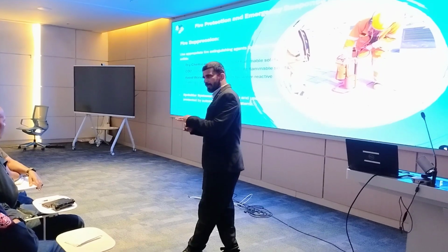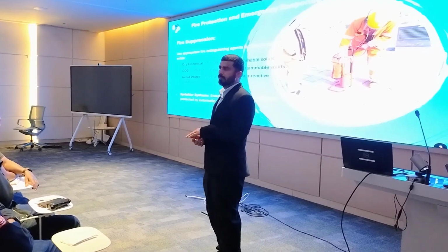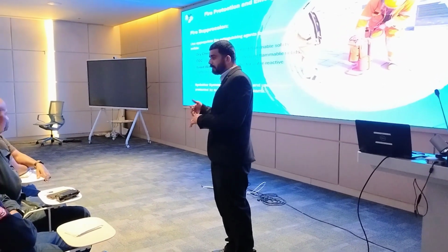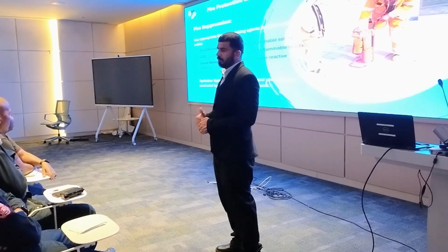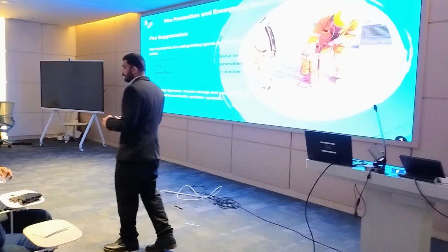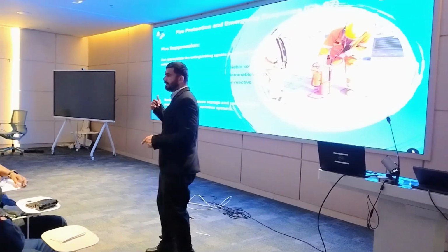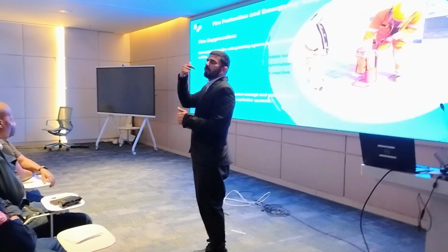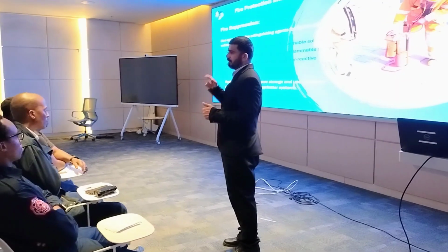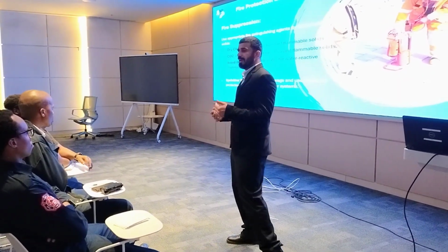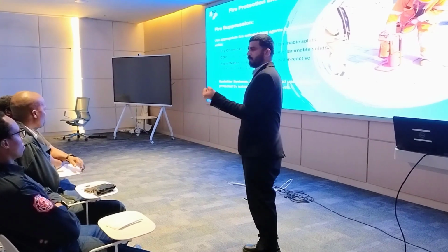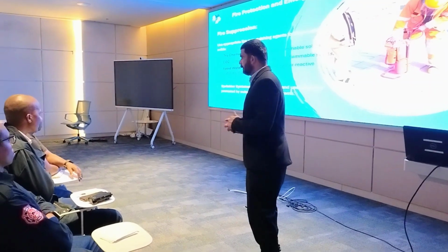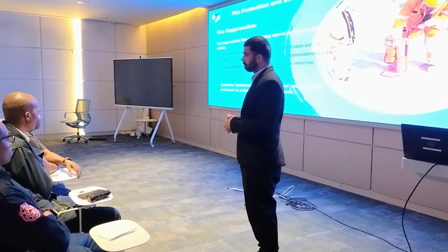Second, we have firefighting equipment: a fire hydrant, CO2, and DCP trolleys. This depends on the use and on what kind of material it is, because as we just read, some flammable solids react when we throw water on them. If we don't know what kind of material it is and we start firefighting, there could be an explosion or a reaction of that flammable solid that affects us. You got it?